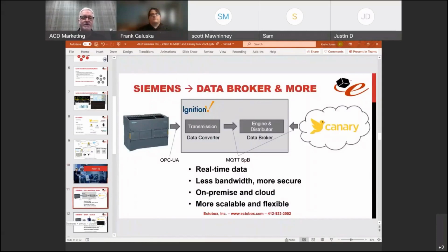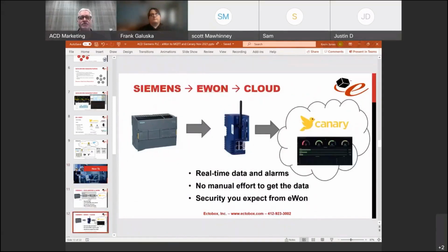This time, we're going to talk about how to use the Ewon Flexy product and how it's connected to the Siemens PLC to send data out. Keep in mind, we've worked with a number of OEM companies over time, and when we see the Ewon Flexy put in place, very often we'll see service departments reaching right into the Flexy over a secure connection to get data out.